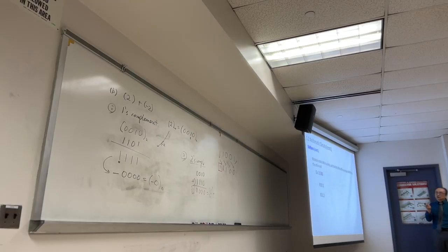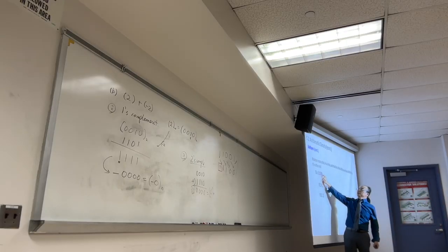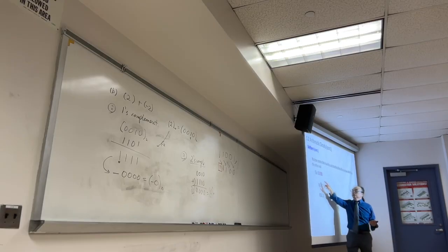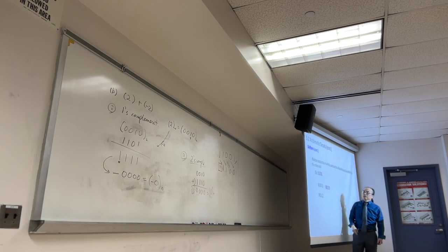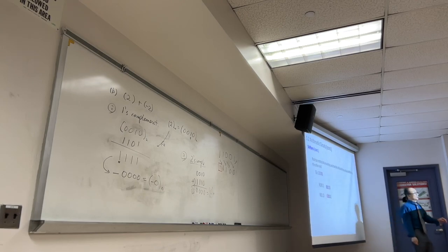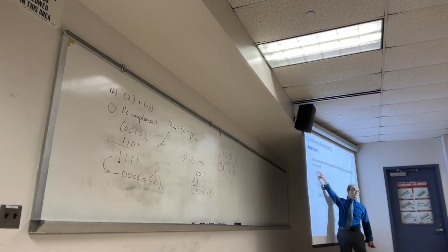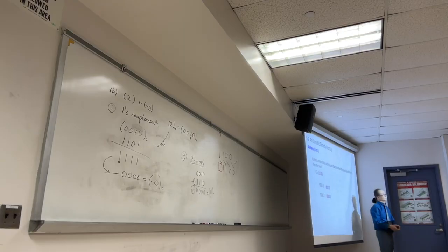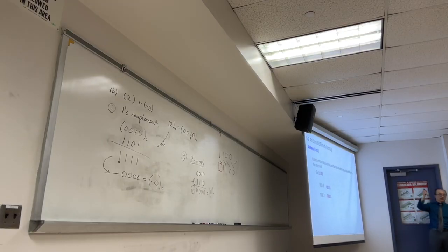When you rotate to the right, you push everything to the right by 2, but anything we lost, we put back into the front. So after shifting right by 2 bits, whatever gets pushed out of the number goes into the most significant bits. Similarly, rotate to the left: shift left by 2, and bring whatever was on the most significant bits to the right. That makes sense, right? Rotate within the number. We'll see this again later.